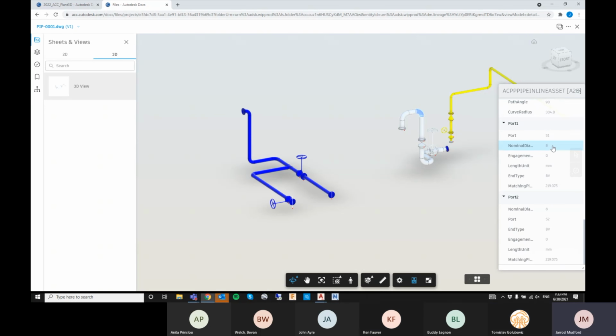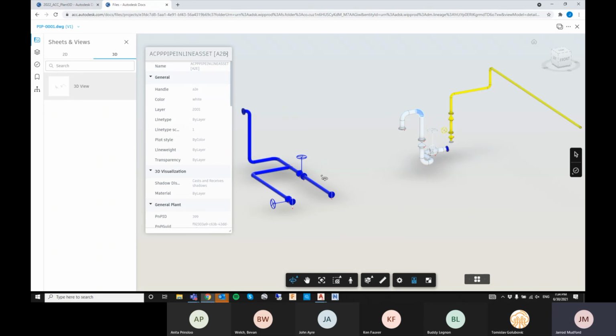But we can see this in Navisworks as well. So does this file here view references? Tom, if you referenced the equipment into this piping file, let's just do an overlay. Because depending on how people run their Plant3D projects, are they doing one pipe per file? Are they doing one service per file? Are they wanting to measure between two different files?